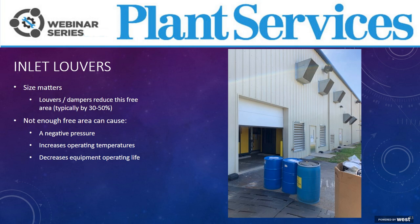The picture shown here includes inlet louvers at the bottom and discharge ducts at the top. So that's what you see on the right-hand side. You can also see a roll-up door to the left. When roll-up doors are open, like you see here, or partially open, typically there's really not enough fresh air to reliably run your compressed air station. But when it's closed, you may experience overheating. So if you have these symptoms or you notice that in your own facility, likely you don't have enough cooling air inlet, and it just simply needs to be bigger.